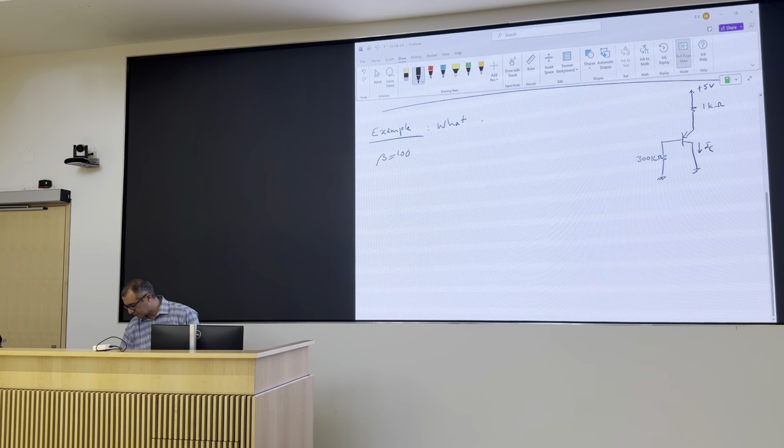remember IC is marked this way. Say a transistor is happily in active region, and for whatever reason it is entering saturation. The first thing you notice is that IC is becoming larger or smaller. So you're measuring IC. As the transistor enters saturation, will IC become larger or smaller? Smaller, right? Because you're pushing current in the opposite direction.